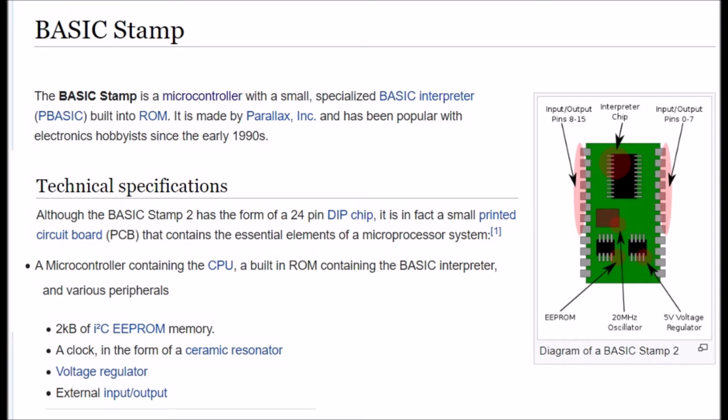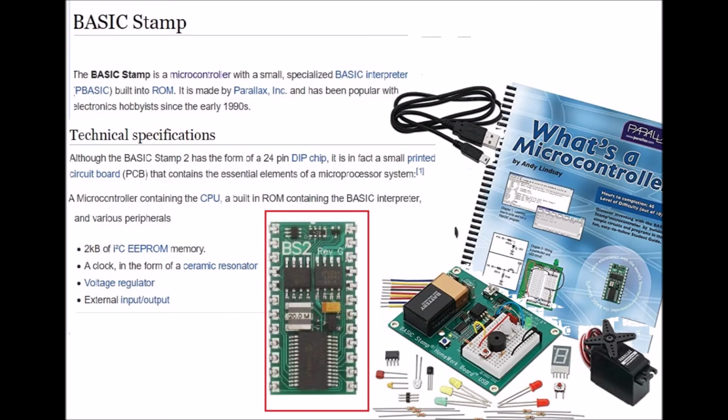The end result is that a hobbyist can connect a 9-volt battery to a Basic Stamp and have a complete system. A serial connection to a personal computer allows the programmer to download software to the Basic Stamp, which is stored in the onboard non-volatile memory device. It remains programmed until it is erased or reprogrammed, even when the power of the stamp is removed. If the power is reconnected, the stamp immediately starts executing the program in slot 0 of 8 numbered 0 to 7.